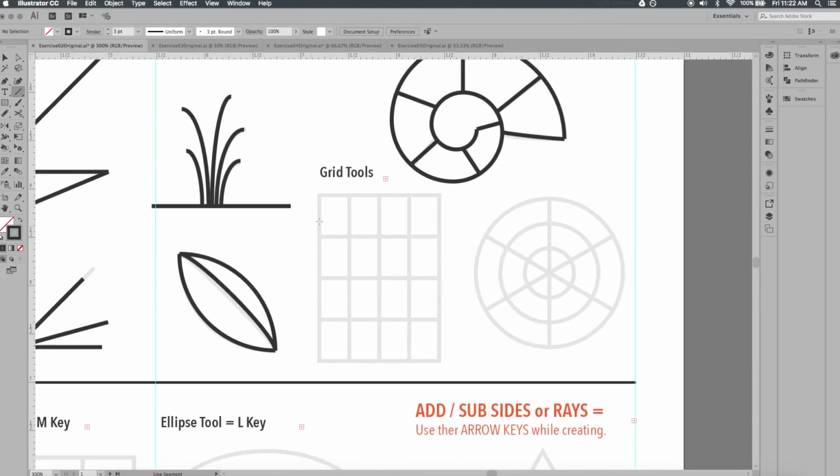Okay, so the last two tools for the line tool group are the grid tools. So the rectangular grid and the polar grid. So the rectangular grid, as you can imagine, is going to make a rectangular or square grid. I'm going to go ahead and click and drag. I'm holding down on the mouse key.